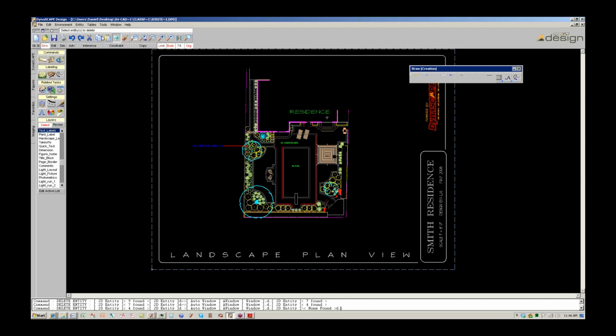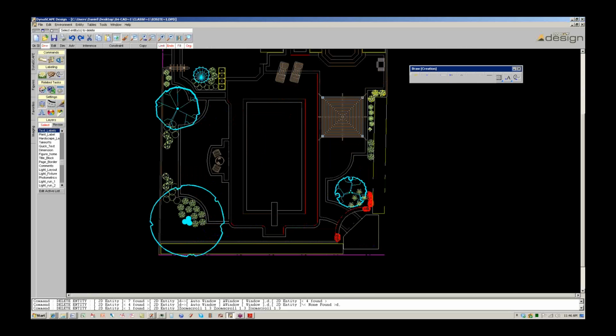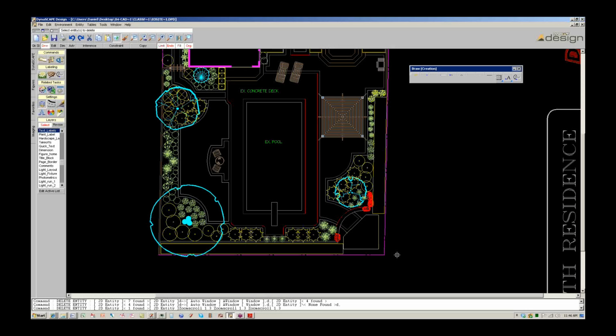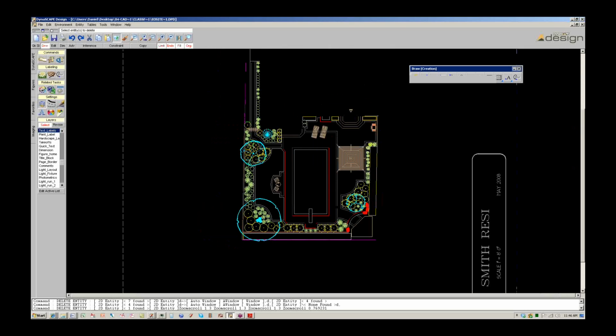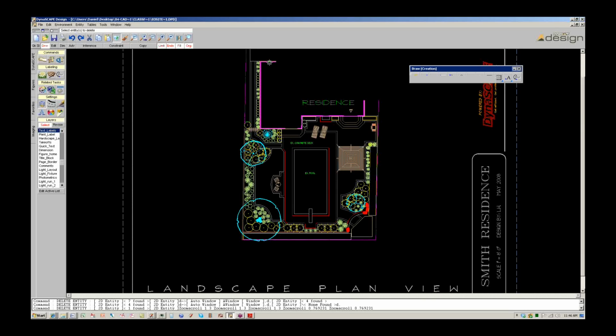It will bring it into SketchUp if you don't delete it, and it'll cause you problems. But in this particular drawing, for example, there's a lot of areas that aren't closed off. The building is one example. So by importing that into SketchUp without actually having a closed building loop, I can't tell SketchUp to make a face out of it. The same with this boundary for this particular drawing.